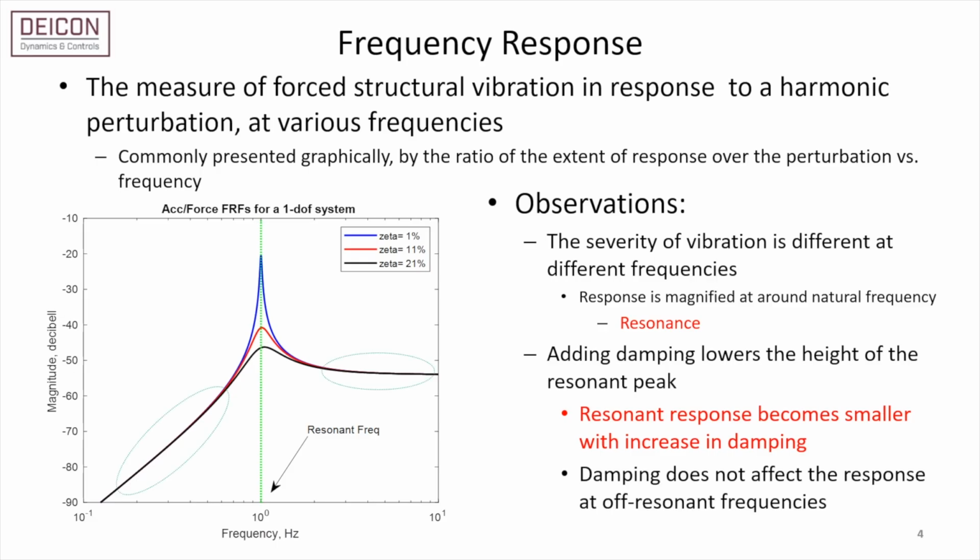3. While damping effectively tames resonant vibrations, it doesn't notably impact the structure's response at frequencies away from the resonance point. This means that damping primarily targets and mitigates the severe vibrations at the resonant frequency without significantly affecting vibrations at other frequencies. Frequency response is crucial in understanding, designing, and/or modifying structures to ensure proper vibratory attributes across frequency spectra.